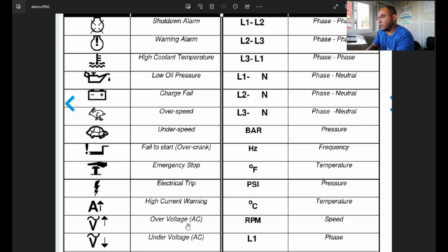Of course, you have to look at the configurations. If the configurations are correct, you look at the voltage output using the multimeter. It should be the same voltage as your configurations. For example, if your nominal configuration is 400, your generator output voltage should be 400. And of course, you have to check that if your generator wiring is 3-phase 4-wire, your configuration should also be 3-phase 4-wire.